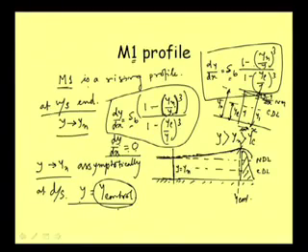horizontal, but that is not correct, because here our y, that is depth, we are measuring with respect to channel bottom, not with respect to a horizontal datum. We are not measuring with respect to a horizontal datum. So, when we are saying that dy dx is equal to 0, means depth with respect to channel bed is not changing, depth of flow is not changing, rather with the direction of x. So, it will become parallel to the bed, not horizontal, it will become parallel to the bed at upstream end. Okay.